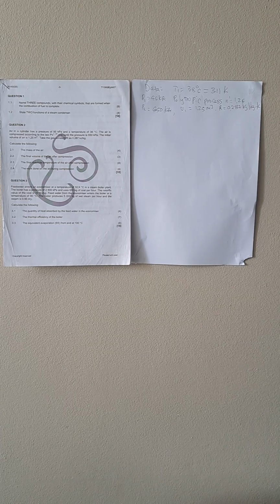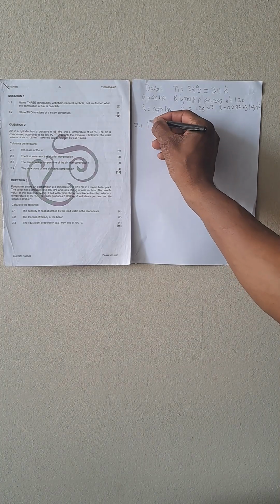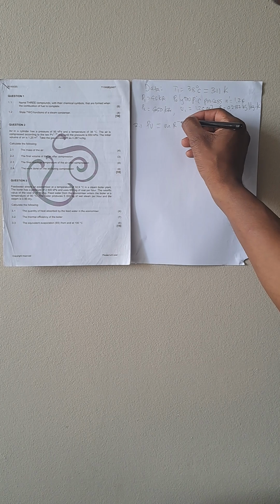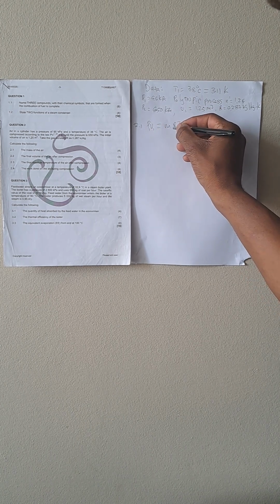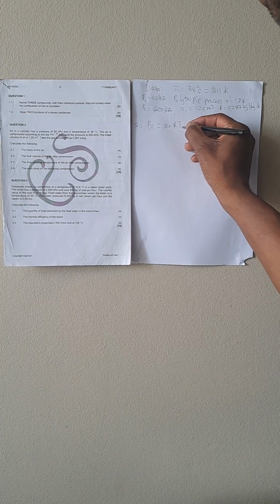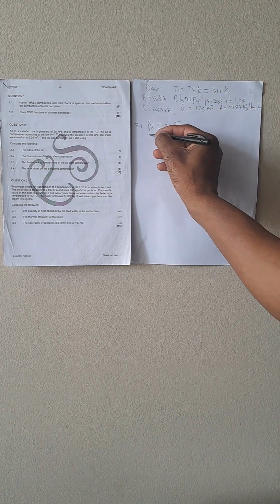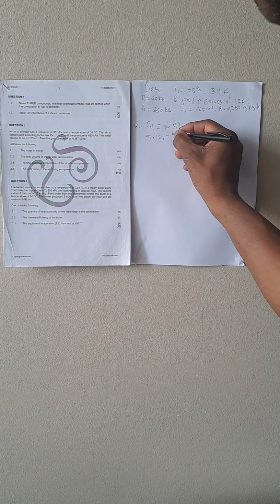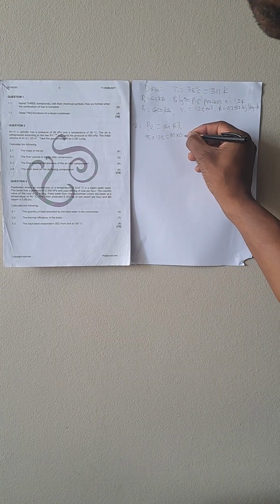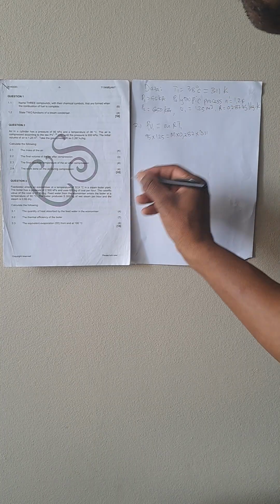The first question, which carries 4 marks, says calculate the mass of the air. Therefore, on 2.1, we can use our formula PV equals MRT. We have P1, V1, the gas constant and T1, but we don't have our mass. So we can substitute: P1 is 95, V1 is 1.25, we are looking for M, gas constant 0.287, T1 is 311.